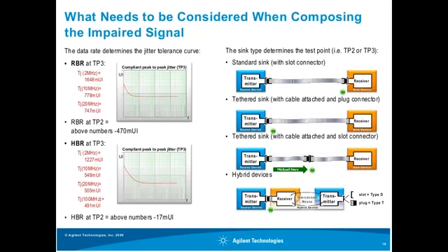The last type of sync devices are something called hybrid devices, and you could say these are maybe active cables. So a hybrid device typically plugs directly into a transmitter and has directly a receiver connected. And then there's some sort of interconnect between another transmitter, and you could think, for example, of an optical connection between that receiver and that transmitter. And this would plug again into a monitor, and the hybrid device would be something like an optical cable. But when testing a hybrid device, you would test the receiver inside that device.